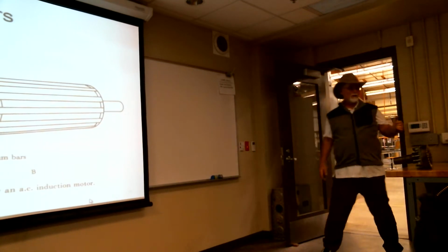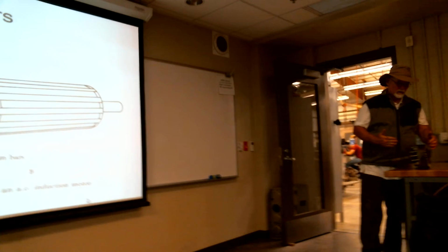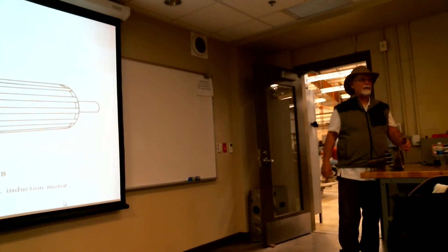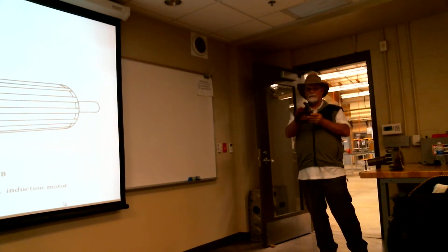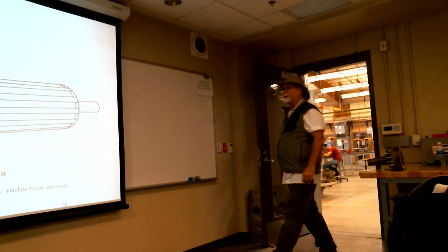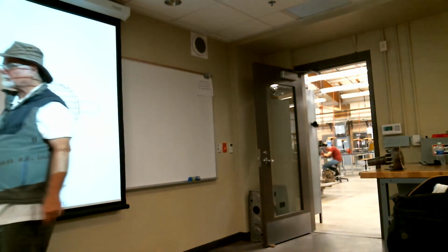Now I have to make a whole bunch of these plates so that the magnetic fields induce current this way, but not this way. Okay, so we're going to magnetically separate the plates by just a little bit. There's not much here, it's just a little bit of light shellac. Okay, so kind of like a little squirrel cage.